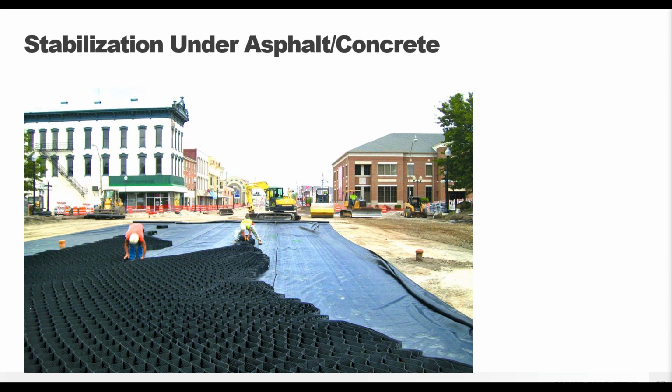So that same mattress effect from the GeoWeb panels that we had been discussing still applies here, with the system helping to bridge soft soils and adding strength to your weak subgrades. When it's used as a base layer, those stiffening effects create that nice uniform system. That's what we like to hear, uniformity. And that's going to be translated up through the surface layer. So it's going to keep paved surfaces stable and in place, reducing your overall maintenance requirements.